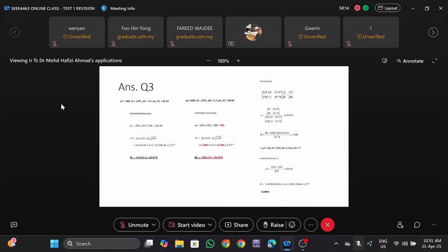All right. So firstly, you need to calculate A and B because this is gas. You might see that the temperature measured is 23, so 273 plus 23 becomes 296. 273 plus 20 degrees C becomes 293. The first table has pressure at 300, so when we do temperature correction, it becomes lower, 296.96. And distance becomes 2.1. We always use centimeters. Please use centimeters.